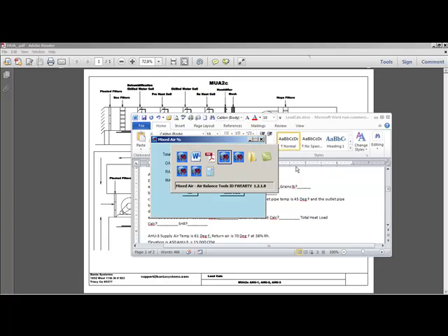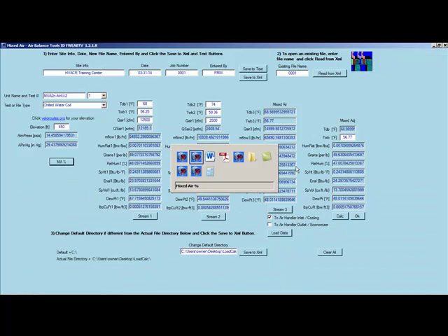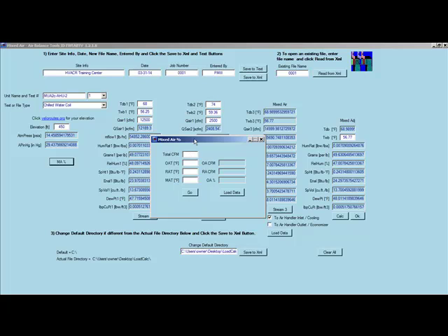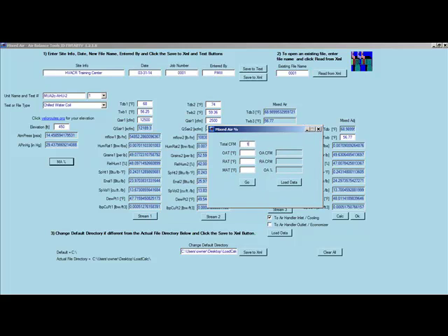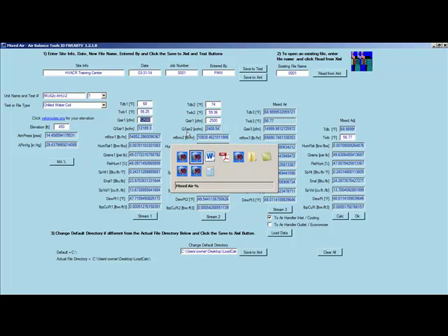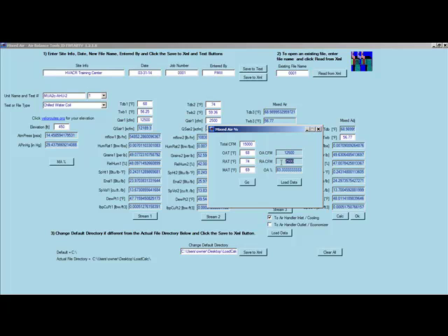So we're going to go ahead and bring in our mixed air. And we know we have 15,000 CFM. We have 68 degrees, 74 degrees, and 69 degrees. That gives us 12,500 and 2,500 coming in from return.